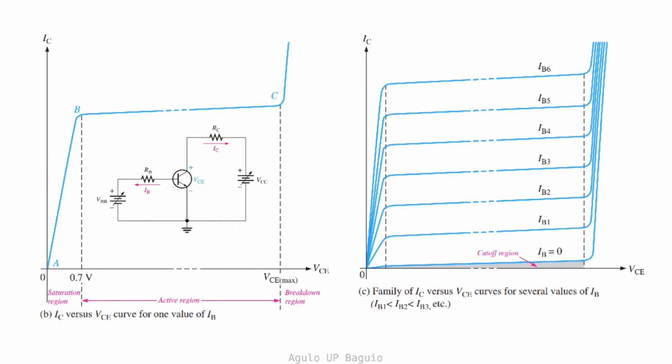its operation. Saturation is the state in which the collector current has reached a maximum and is independent of the base current. As VCC is increased and VCE exceeds 0.7 volts, the BC junction becomes reverse biased. Most of the voltage is then dropped across VCE because the barrier across BC begins to thicken. Thus, the current IC hardly changes or increases slightly, and the expression relating the base current to the collector current via DC beta is no longer valid.